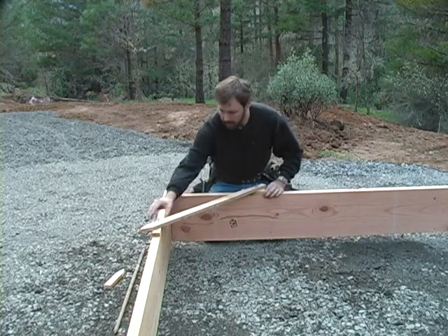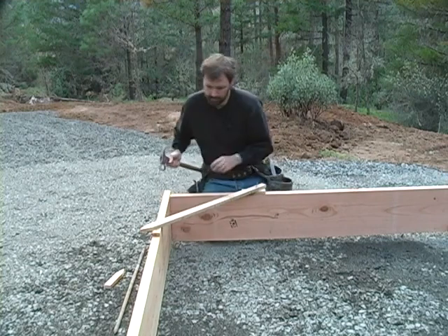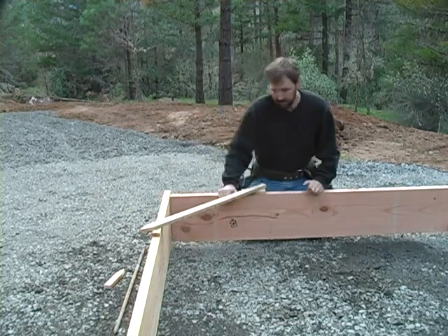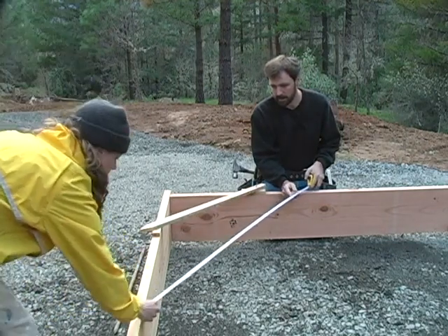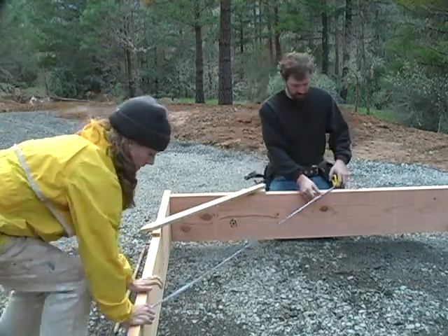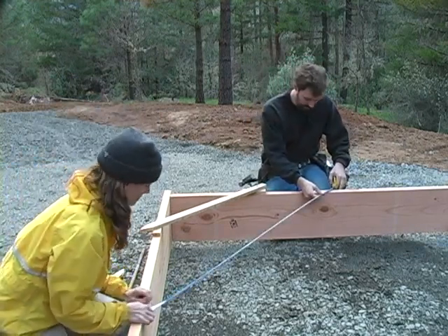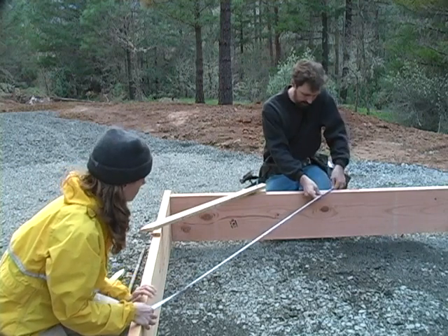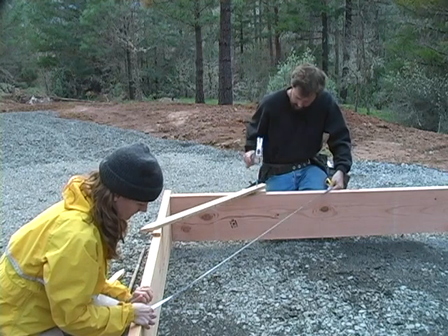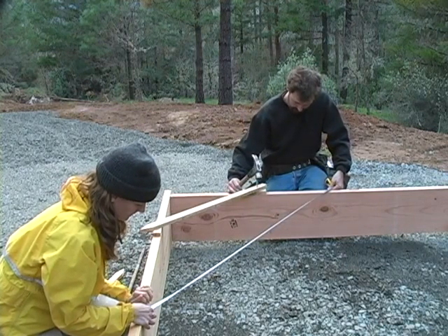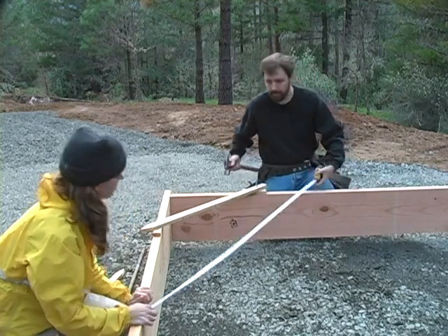So what I'll do here is just tack one side in place, and then again with a helper holding one side of the tape and using their knee against the form board there, I'll hold mine end here. And we're just giving a little bit of a tweak here because we know it has to do with the bow rather than it actually being the building out of square. Now we're right on the mark there. Get my brace in place. And that's got it.